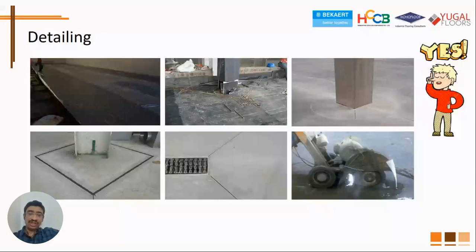Usage of plastic sheet or LDP sheet is imperative to reduce the friction between the subbase and the grade slab. The second image shows restraining reinforcement, or what is known as auxiliary reinforcement. Also notice some isolation around the column pedestal that has been provided, because you don't want to have the structural superstructure interaction going to your grade slab, because the grade slab has to be designed for completely different loads. It cannot take the structural loads coming from columns and walls.